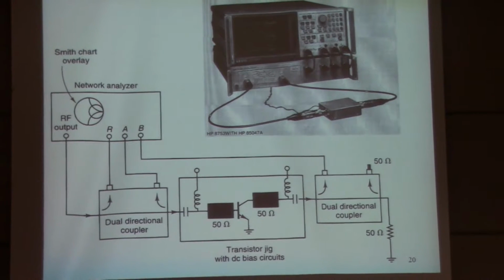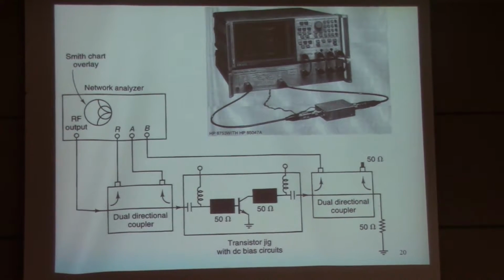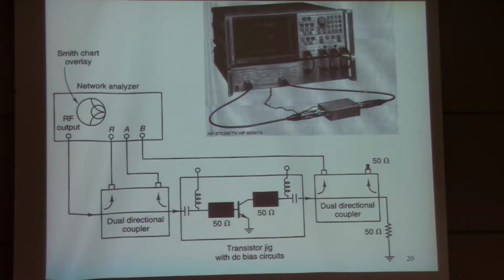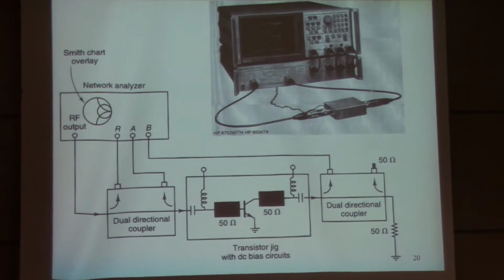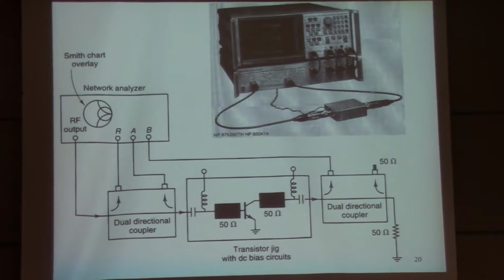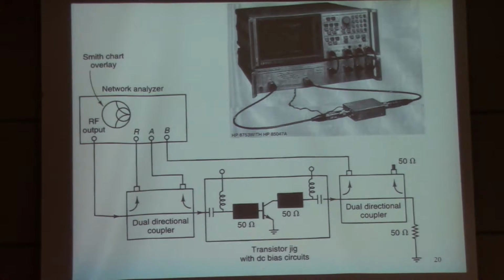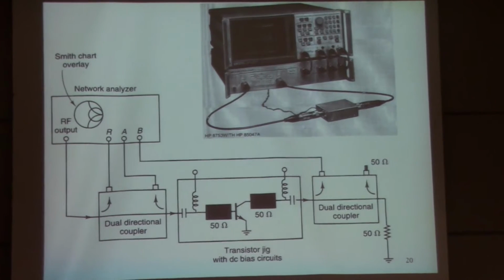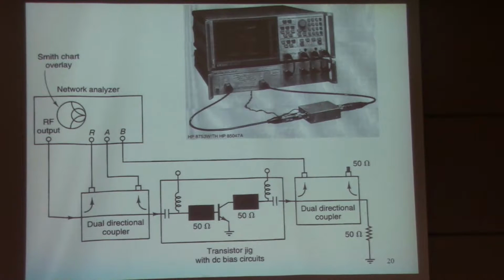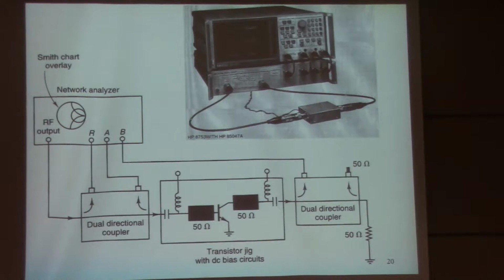Okay. And before you do the measurement, you need to zero, right, to see if your system is working properly or not. That is where you use the standard, which is you have 2 lines matched with the impedance. That's the only standard actually you need. It's a magic, right? You just need to know that these 2 lines are matched. Then you can rigorously characterize your system and make accurate measurements.